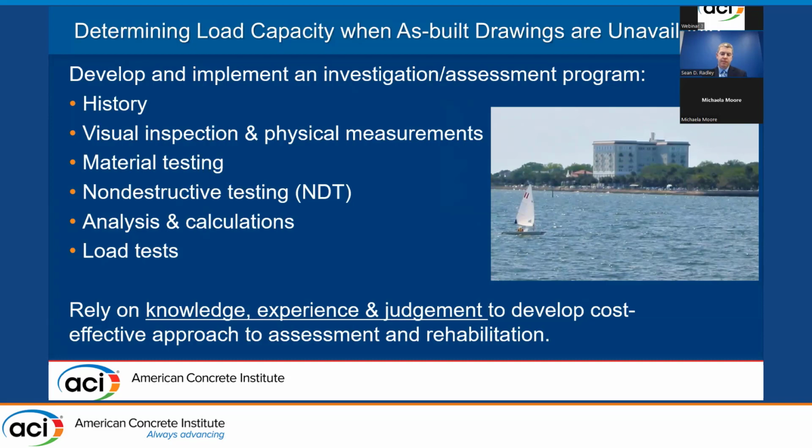in looking at this development and implementation, the first thing you do is develop and implement some kind of investigation or assessment program. And for that, you're looking at many things. I can't overemphasize history, just history of buildings in the area, visual inspections along with physical measurements, material testing, non-destructive evaluation. And yes, you can use a lot of NDT in investigating the buildings.